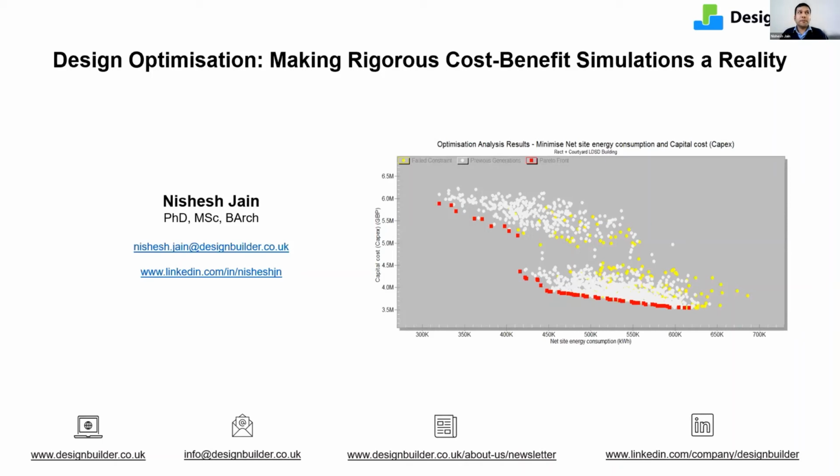So it's a balance between time and results. For example, in the example which I showed, I stopped the analysis at about 1,000 iterations, and that was good enough to give me results. I did run it for another 2,500 runs, which took significantly more time. But between those 1,000 and 2,500, I did not get any new interesting insights.